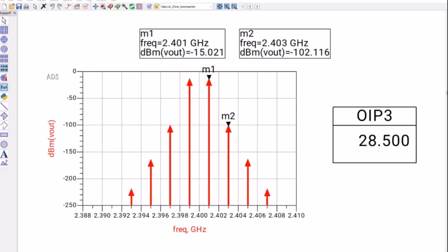Which design technique will be effective, like cascade, cascode? I mean, that's a difficult question to answer. That depends on what implementation you are doing, whether it is MMIC, RFIC, and so on and so forth. So in MMIC or RF board, you don't use cascode for sure, but you can of course use multi-stage LNA design. But if you're doing RFIC, yeah, maybe cascode might be used.